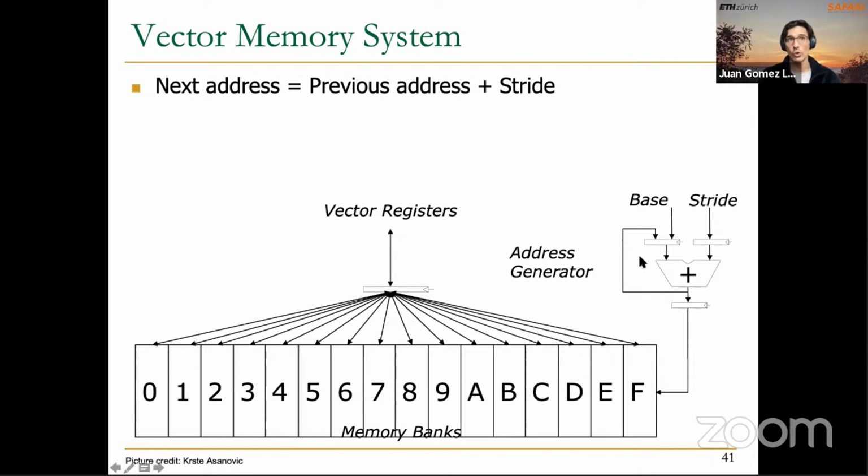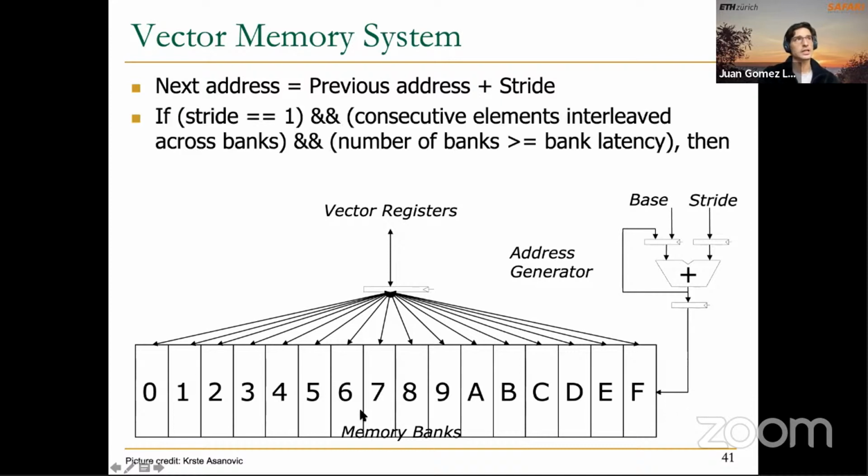Let's say our load store unit has this adder that gets the base address of array A, gets the stride, and cycle after cycle adds the stride to the address value that we have here in this accumulator. And then we send it to the MAR of the different banks and start accessing the banks. So that's essentially what we are doing here.